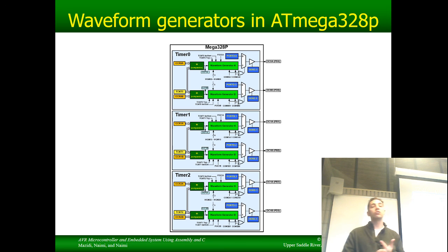You might want to use port C for the row. You might want to use the upper half of port D as the column, or vice versa. Find 2 groupings of 4 contiguous bits, and you'll be pretty happy. Keeping in mind that these pins are already taken.